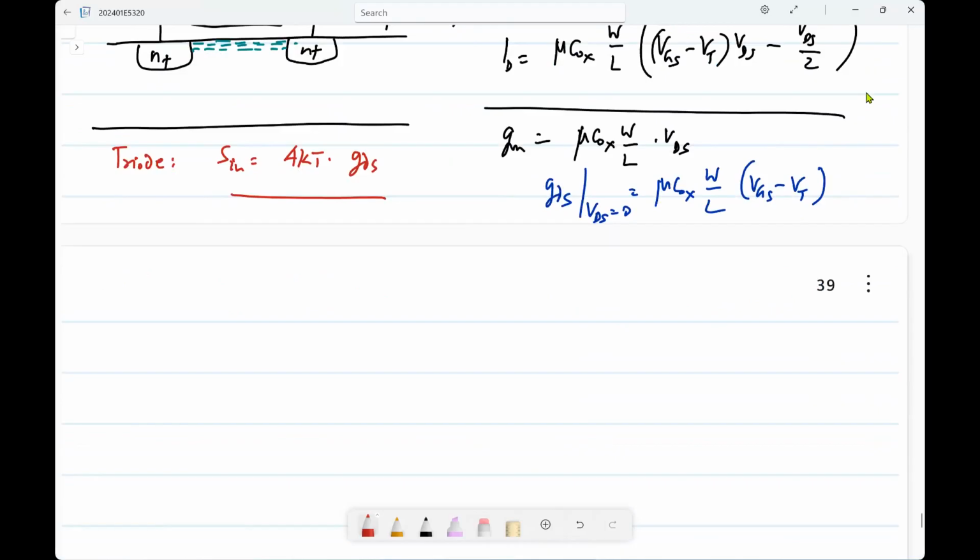First of all, we write these expressions saying that this is in the triode region, that's in the saturation region. It's not as though throughout the triode region this expression holds and suddenly it jumps to the other expression. It continuously changes. I'll just show you the total expression, but this can be used approximately anywhere in the triode region. But of course, if you take VDS very close to VGS minus VT, but just less, it is still technically the triode region. Then if you use the GDS from that operating point, it will not be correct. Exactly. So this is close to VGS, deep in the triode region. This is correct, and well in the saturation region, that's correct.